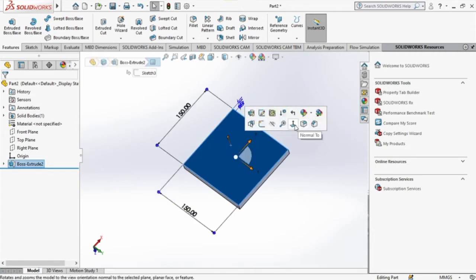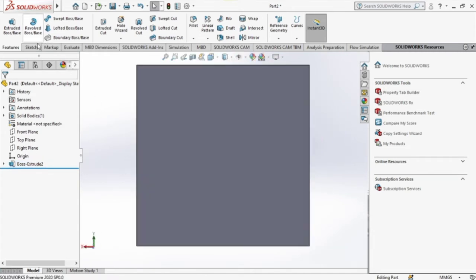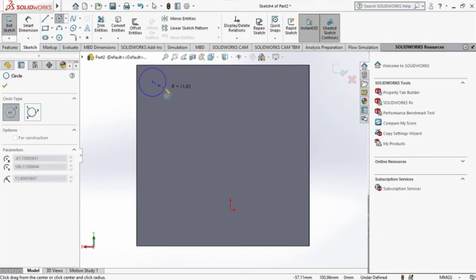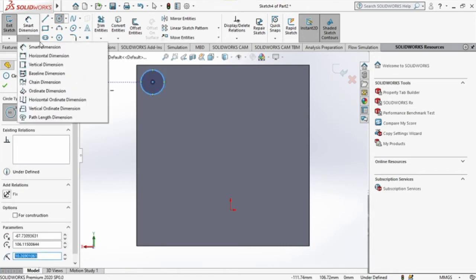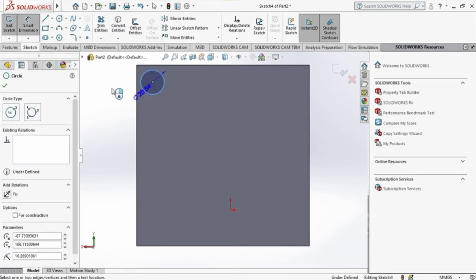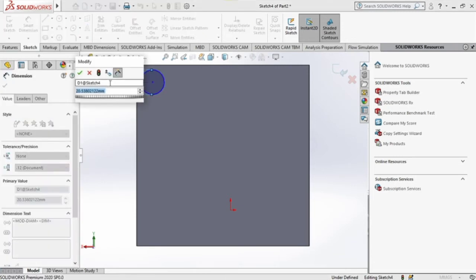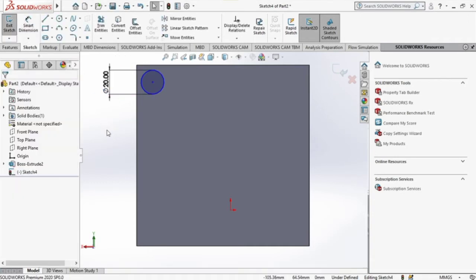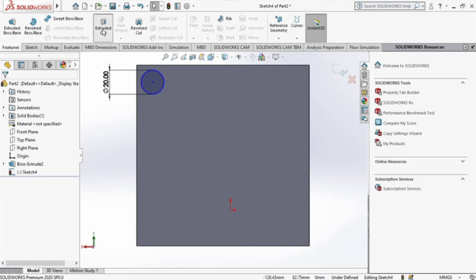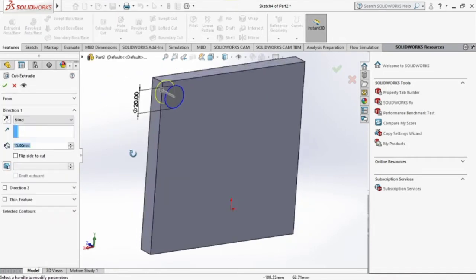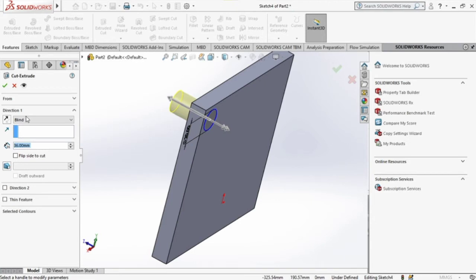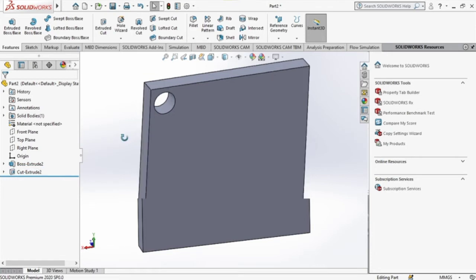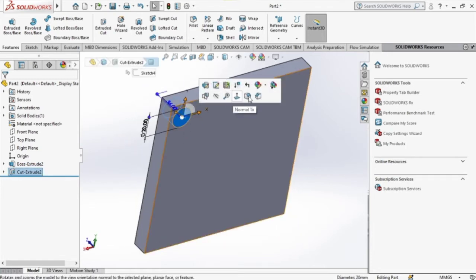Right, so what we do is in the corner of the square we draw a circle with a radius of 10 millimeters and we cut a hole using the extruded cut design. So I'm sure we know what the procedure is for now. Okay, now let's say we wanted to cut 15 more holes, something like this. It will be a bit tedious for us to start designing this over and over again. So this is where the linear pattern design command comes in.